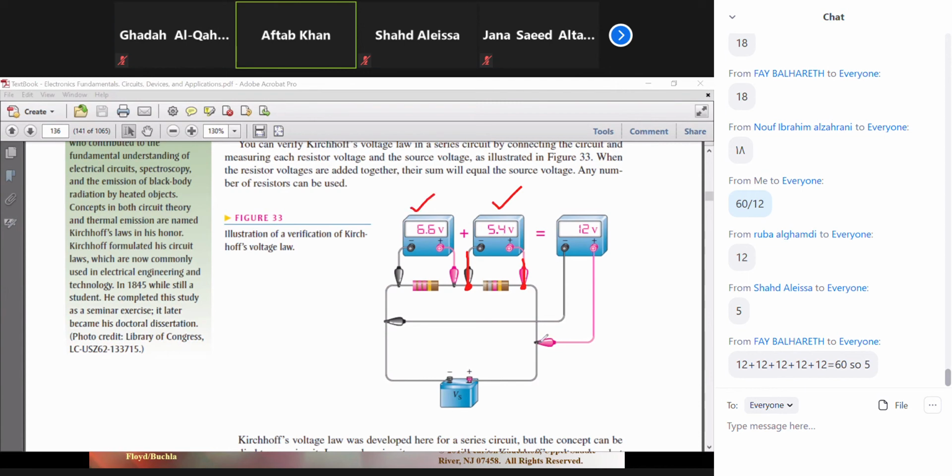And if I connect here and here, actually we are connecting to this battery. It is the same connection from here and from here. So it is giving the total voltage. This is giving the voltage across the resistor. So this is what we call parallel connectivity of the voltmeter. So the voltmeter is always connected in parallel.